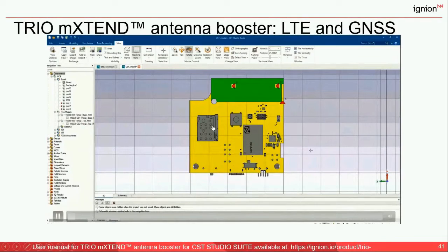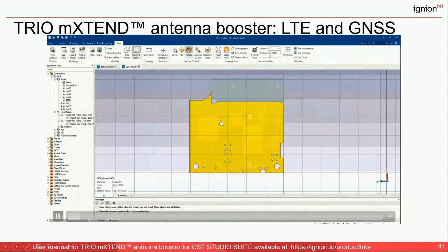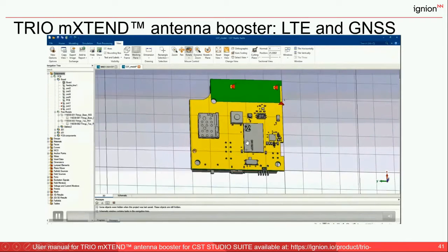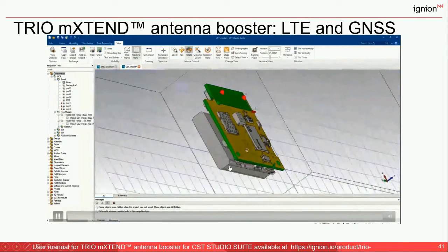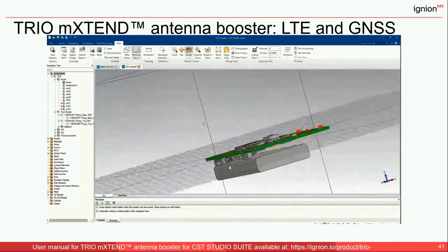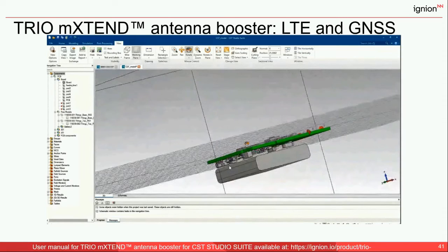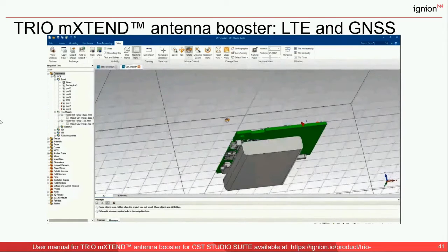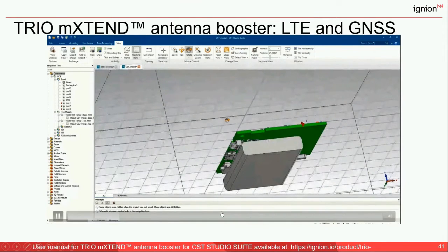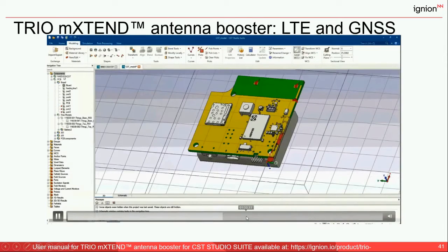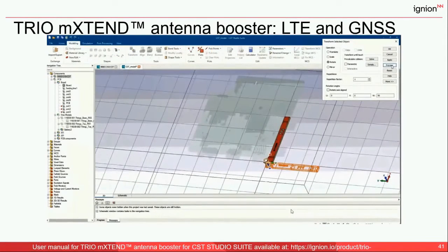which is fully populated. In yellow, we have the ground plane. In green, this clearance area, place for the SIM card, the transceiver. You can even model the battery, and you can do your own stuff. And with the advantage that now you can import our antennas into your software. Any kind of virtual antenna products can be imported, and you can design and do your own parametric analysis, enlarging the ground plane, putting the battery in one place or another place, and at the end optimize the performance.